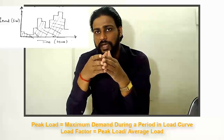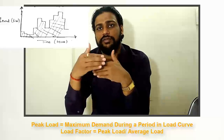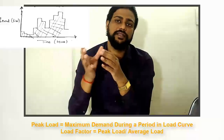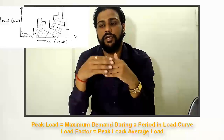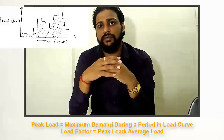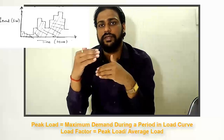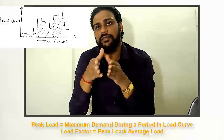It is possible to have a load factor as high as possible, that is, the average load should be as close as possible to your maximum or peak load. The reason is that if you're talking about large power plants, the power plants would be designed considering the average load. If I'm designing my power plant for 100 kilowatt of supply, and I have a peak demand of 150, then I would have to keep that 150, because that demand is happening only for a period of 2 or 3 hours in a day.